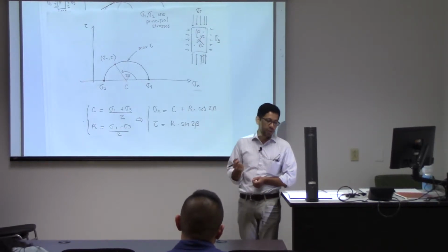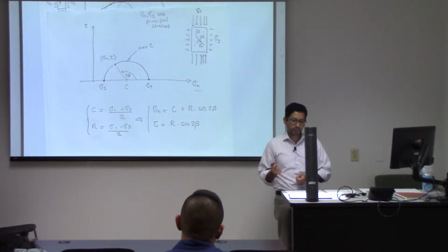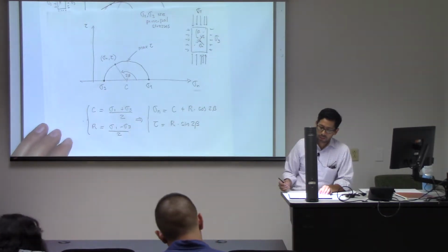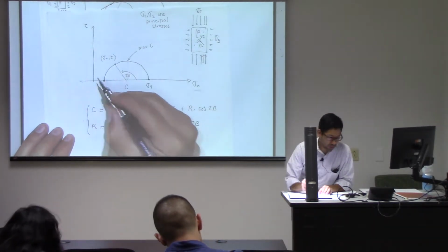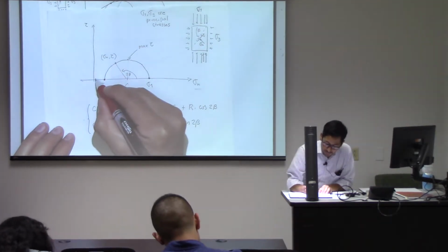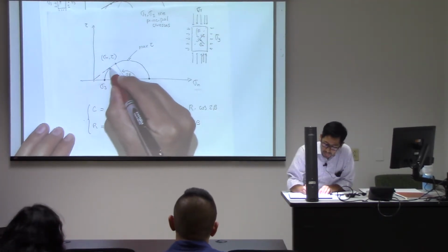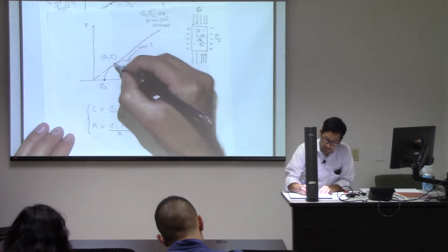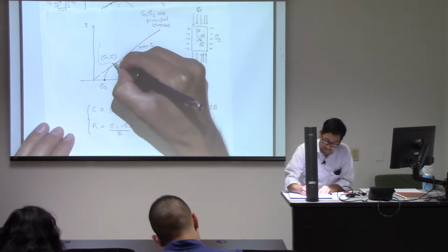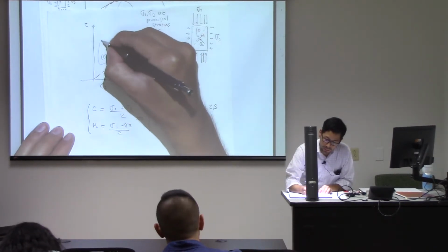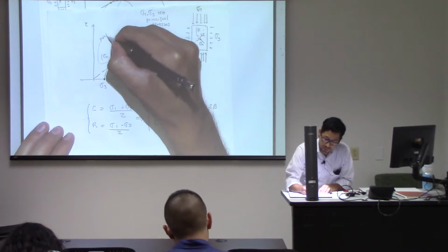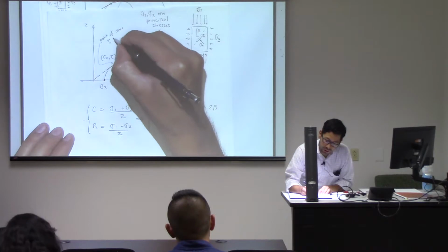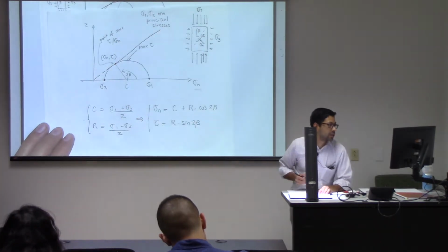Because of that frictional strength, the failure does not depend on the maximum shear stress, but rather on the point of, if this is a shear failure, this point over here, this is the point of maximum ratio of shear stress to normal stress.